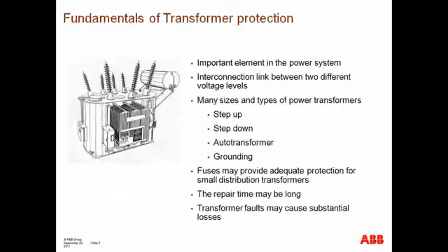As most of you know, the power transformer is a very key and important element within the power system. Power transformers enable more efficient transfer of bulk power. One of the basic functions of the power transformer is to step up voltage to a level high enough that you can carry more real power flow through a particular corridor without having to send as much current as you would otherwise have to with a lower voltage. What that allows us to do is reduce our resistive losses over that particular transmission line. Thus, we're able to transmit power in a more efficient manner.